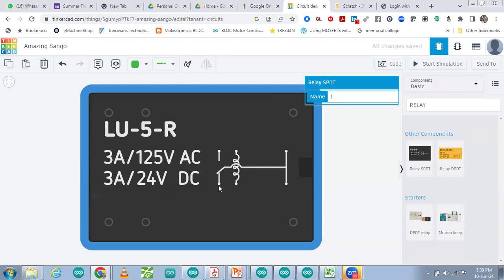And then this one, you can see, is connected by default with the common, that is known as normally closed. So the common wire is connected via a strip like this by default without providing any signal. This one is normally closed, terminal 7. And terminal 6 is normally open. When we provide signal to terminals A and B, then this strip gets connected with this one. So this one is normally open by default.